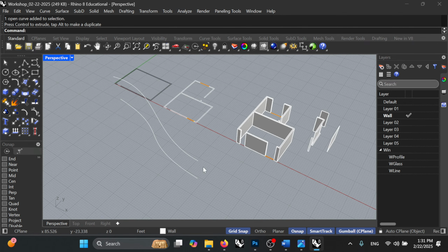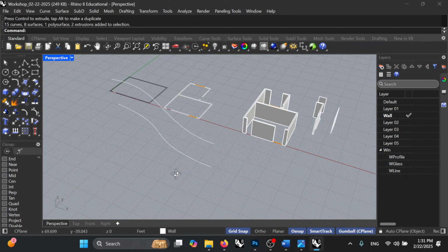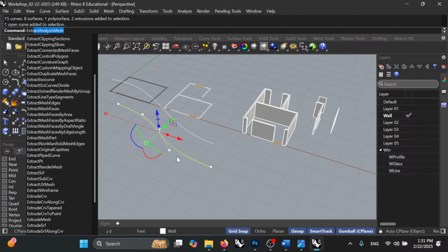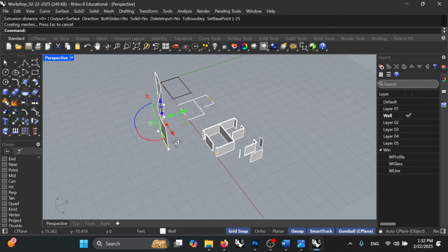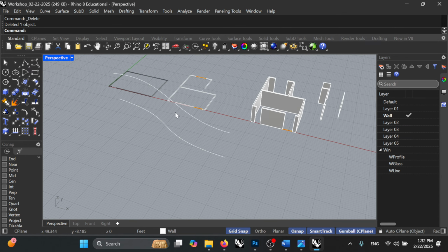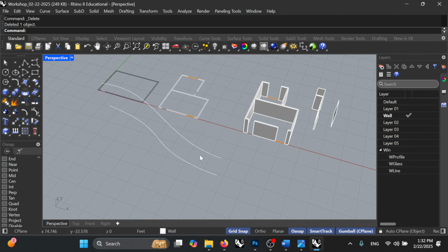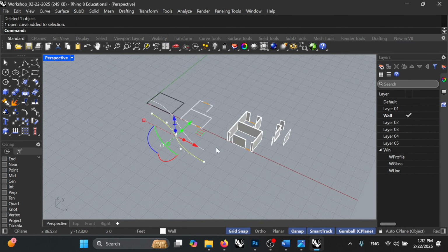a surface in here. So this was a solid geometry because we had it capped, and then there was no open surface. Then we can extrude this. If you remember, extrude and extrude curve. So you can extrude it, let's say by 25 feet. Or you can say that I would like to make a surface between these two curves and then add it to my work. So let me do something really quick.